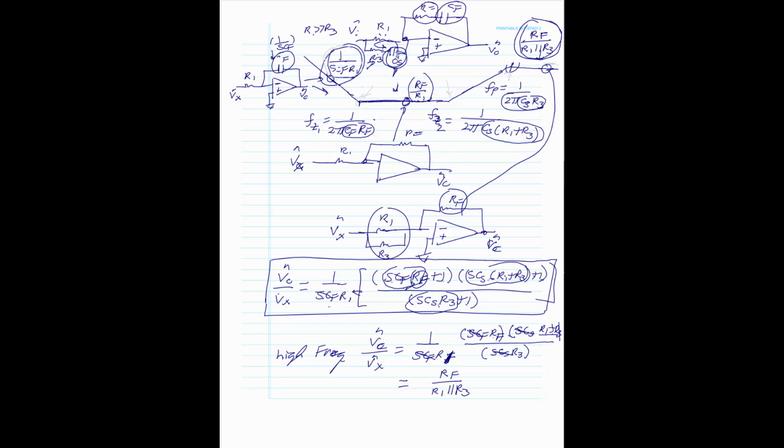So that's our transfer function, and you can see your phase immediately. Like I said, we'll be putting this in LTspice, and you'll see that the phase, right away I have a pole, an integrator, and that's going to give me minus 90 degrees immediately. And then what are we going to have? A zero to start canceling the phase, so we got a phase boost. We got another phase boost, and then we got a phase lag.